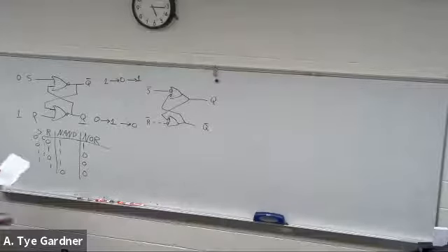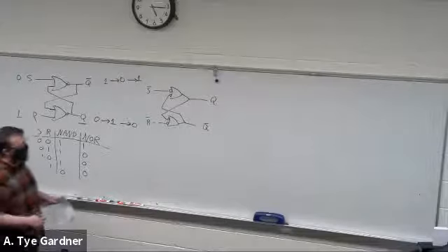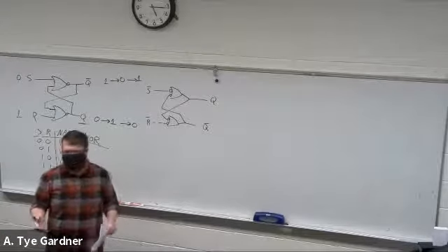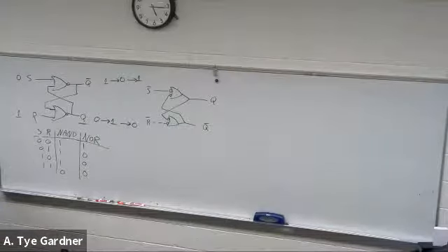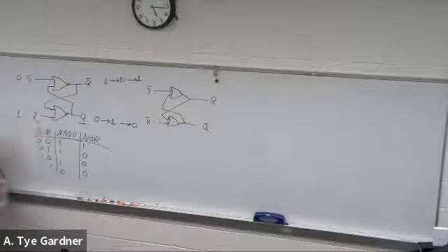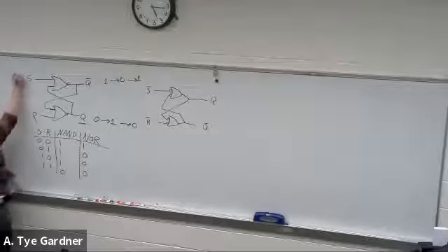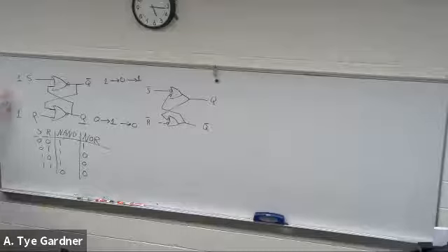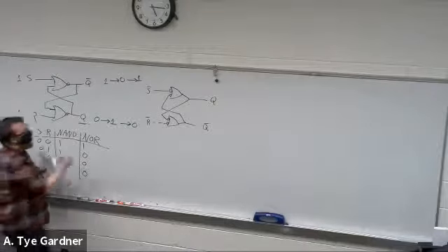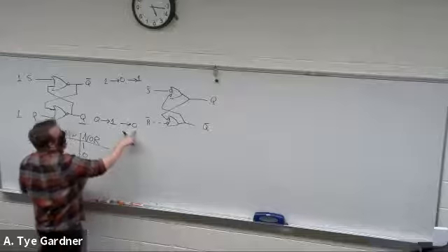So I could ask a question around this. A timing diagram is a really common question that I would end up asking and say, given the waveform for the following set and reset, figure out what happens. Well, let's do kind of that here. So I just said we can't set and reset at the same time. Why? What happens? Well, let's check. If I have a 1 here, a 1 here, I'm sitting initially at 1 and 0, let's say.